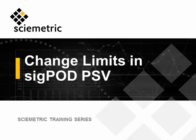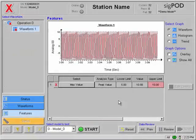In sigPOD PSV, custom features can be configured to meet a variety of test requirements. Each feature checks for a specific characteristic, for example, a maximum value. For each feature, the following parameters must be defined: type, start, stop, upper limit, and lower limit. In this example, a peak value feature type has been configured to return the maximum value of a waveform.